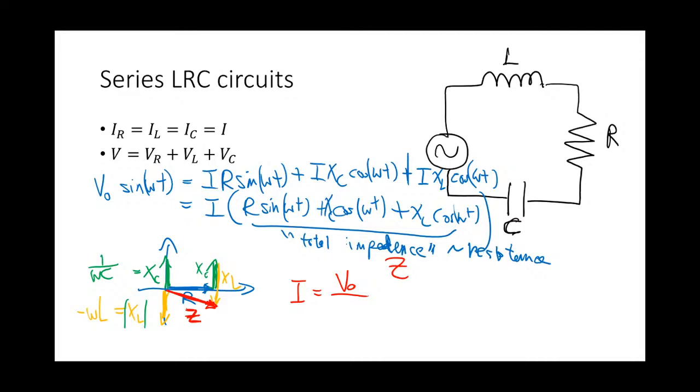So you can represent the final current function as something like that, where alpha, I guess in this case, would be a negative number. And so we can still represent the magnitude of the Z. We take the voltage divided by that, get us the magnitude of the current, and then the current will have a certain phase shift based on wherever this Z ends up.